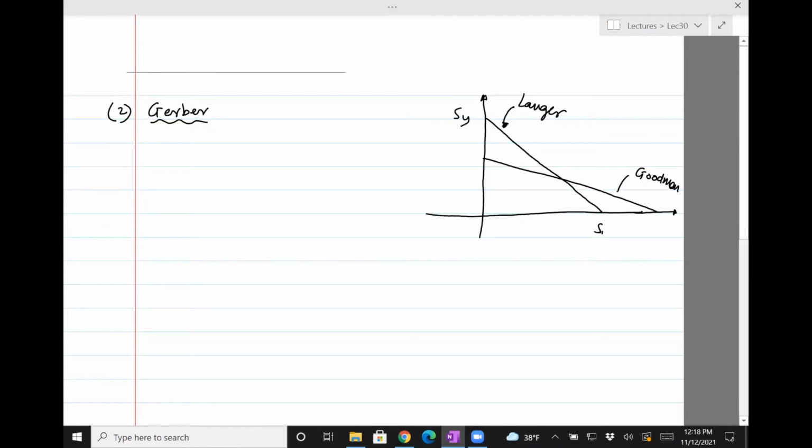SY, SE, SUT. Now we just need to draw a parabola starting at SE and joining SUT.